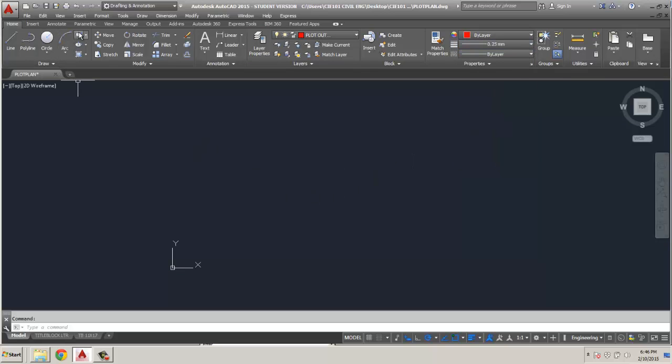So we're going to start with our rectangular tool. We'll start and just type in 0, 0. We're going to key in 5,280 feet, tab, 5,280 feet. Enter. Just double click your wheel. That gets you down. So there's our 1 mile by 1 mile property. Now we're going to divide this in quarters.